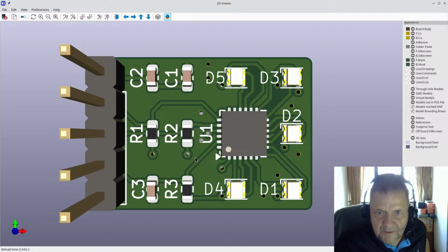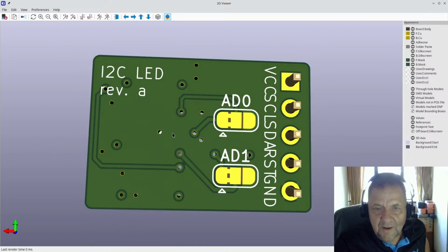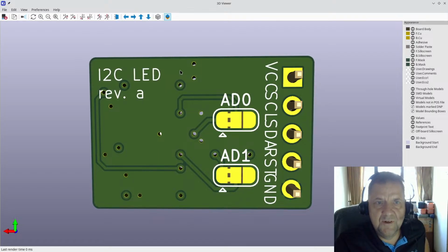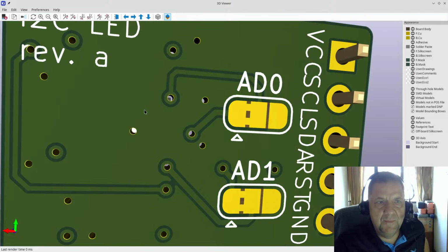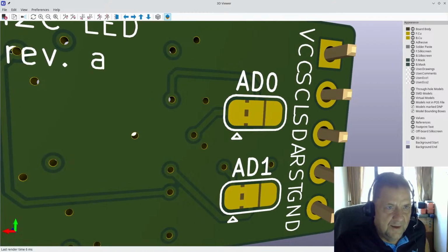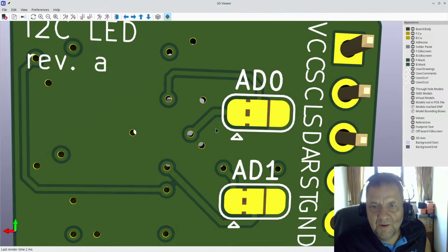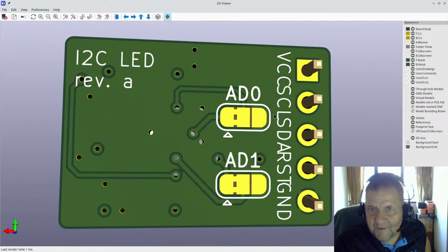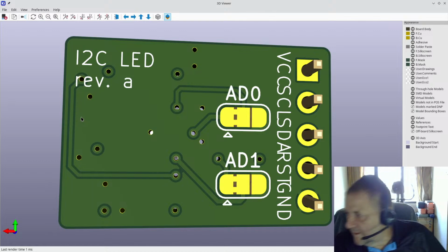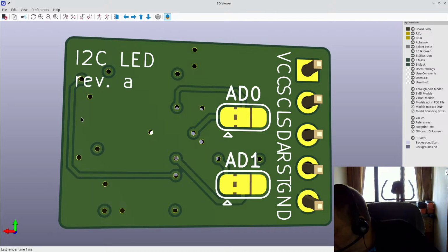What happens with the wires is that they have solder mask. The solder mask is the green stuff, and the hole is really, really small. So what can happen is what you see here, that a little bit of it has been cut off, but it is generally very, very readable, and I never bother with not placing. You could also consider making a larger footprint.